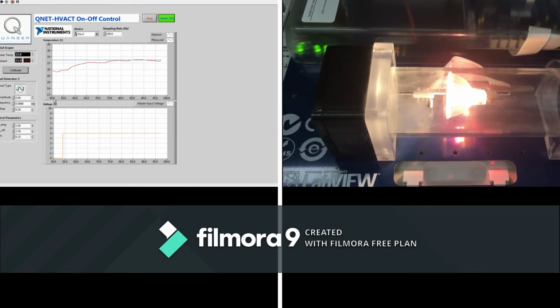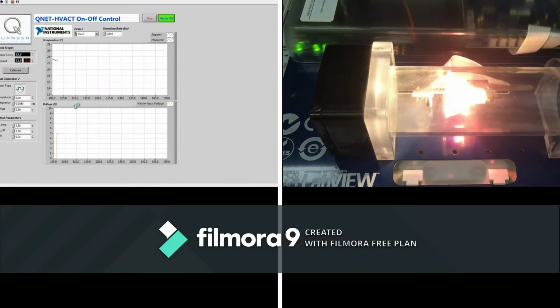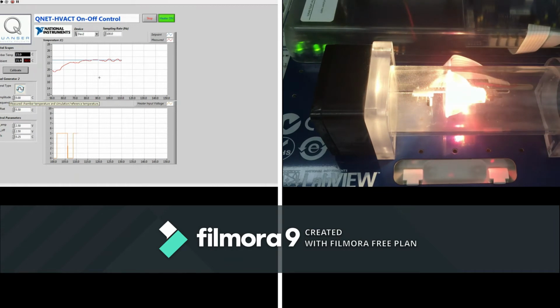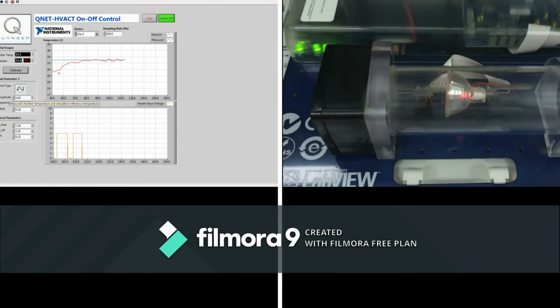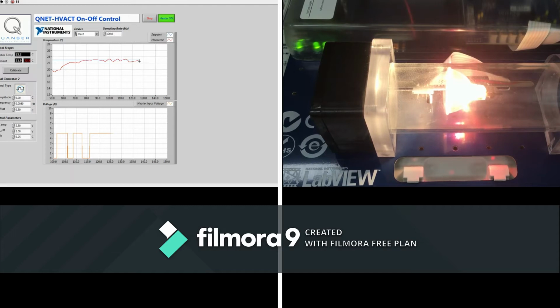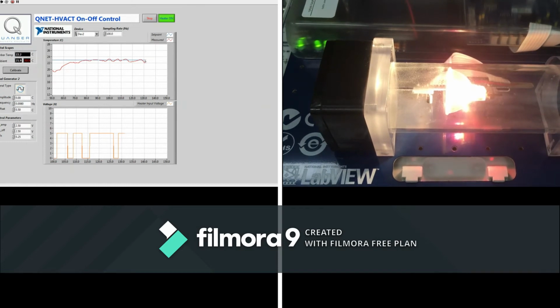You see that from 50 seconds up to 95 seconds, now we reach our value and the heater is off. Of course, we can control our time axis, so let's start from 50. In the beginning, the transient time, the temperature is rising, trying to catch the reference, and at some point we reach our reference point, which is 23 Celsius, and now the heater will be fluctuating, sometimes on and off based on the need. So in this case, we are below the line. That means we need heat. That's why the heater is on.